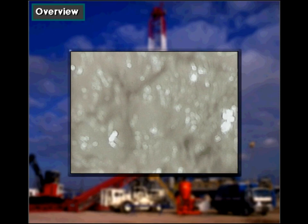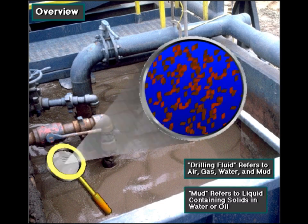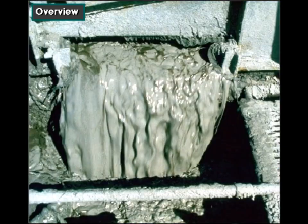Drilling mud, as many people call it, is a vital element of the rotary drilling process. The term drilling fluid includes air, gas, water, and mud. Mud refers to the liquid that contains solids in water or oil. The mud is made up with clay and other additives that give it desirable properties.